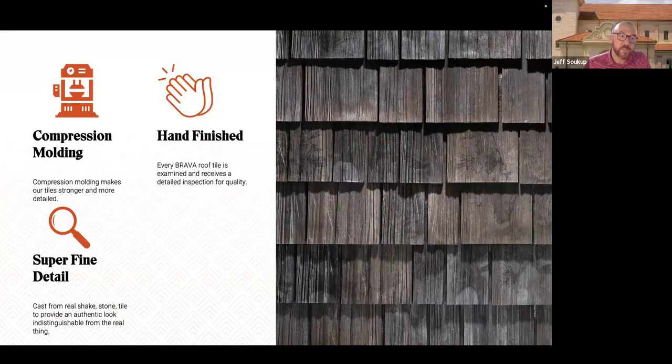We essentially manufacture by heating everything up, combining all the polymers and mineral pigments, and then we extrude what's kind of like a Tootsie Roll, and then we compress it. When it compresses, it creates this natural variegation that you see in our tiles that other synthetic injection molded products do not have, because of how they manufacture.